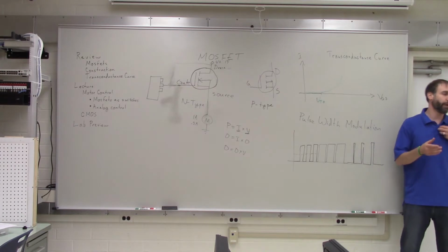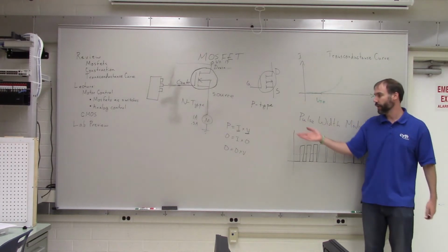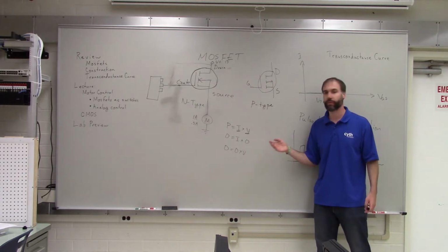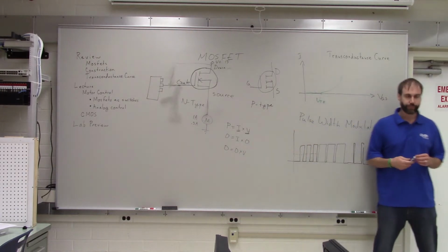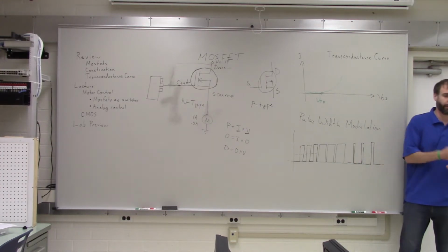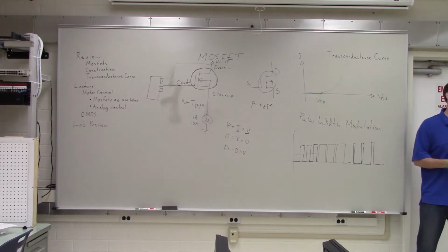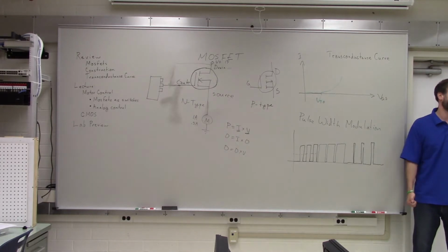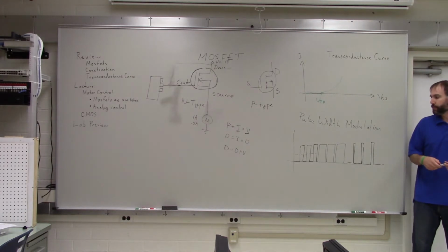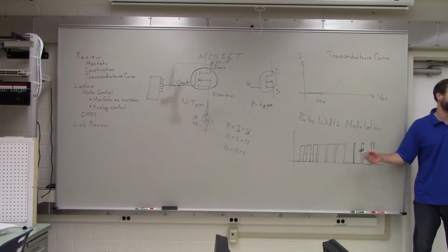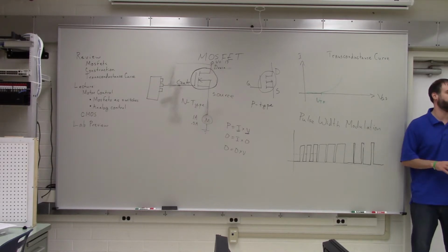And during that time, the MOSFET is in the less efficient region. So you don't want the frequency to be so high that those transitions are happening too often, because that can lessen the efficiency of your device. Certain MOSFETs are designed specifically to have very quick changes, so that they are as efficient as possible for these types of applications.